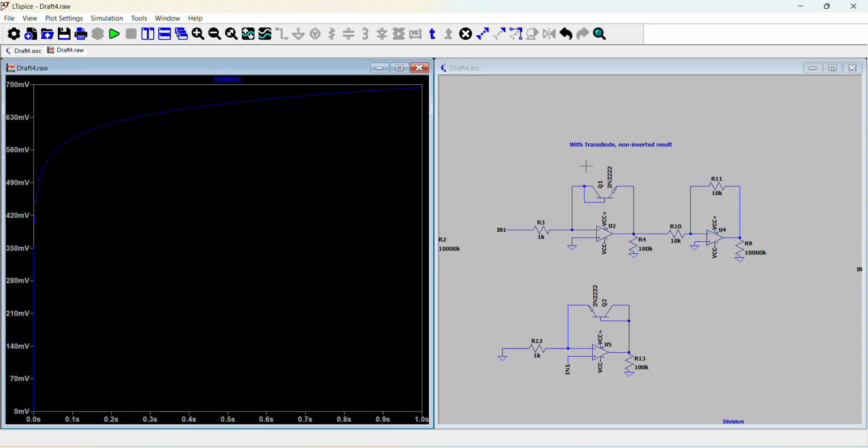And then in a lot of circuits, you'll commonly see the diodes being replaced by a transistor where their base and collector are tied together like this. And the reason why it's done this way is because the transistor is able to model the exponential function better than a standard diode.